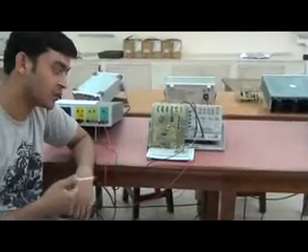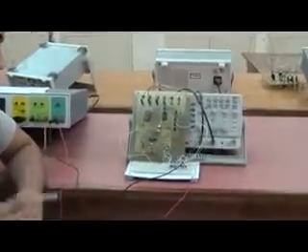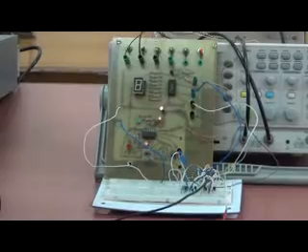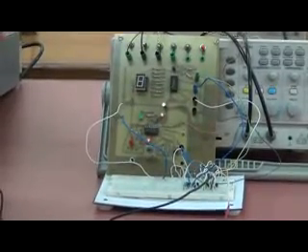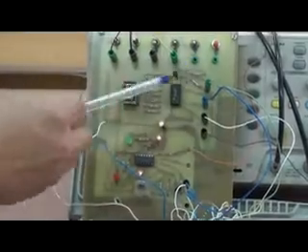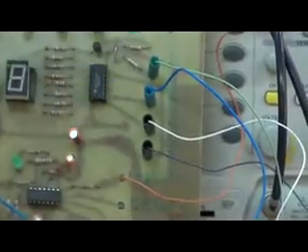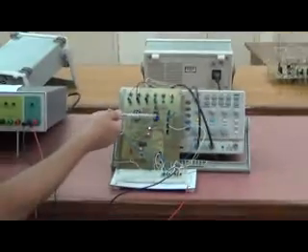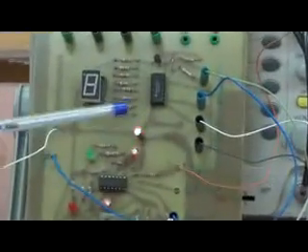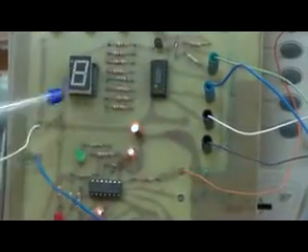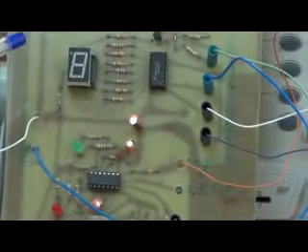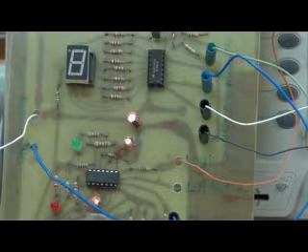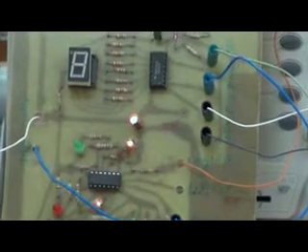breadboard, and will again observe the count values on the digital test board on this hexadecimal display. Since we require only 3 bits to display the output of the counter, we have grounded the 4th pin, that is the MSB of this hexadecimal input, and we will give the output of the counter to these 3 pins of this hexadecimal input. So these 3 inputs will again drive this 7-segment display, and we can observe the count values of this counter on this 7-segment display. Again, the power given to this circuit will be from the power supply.